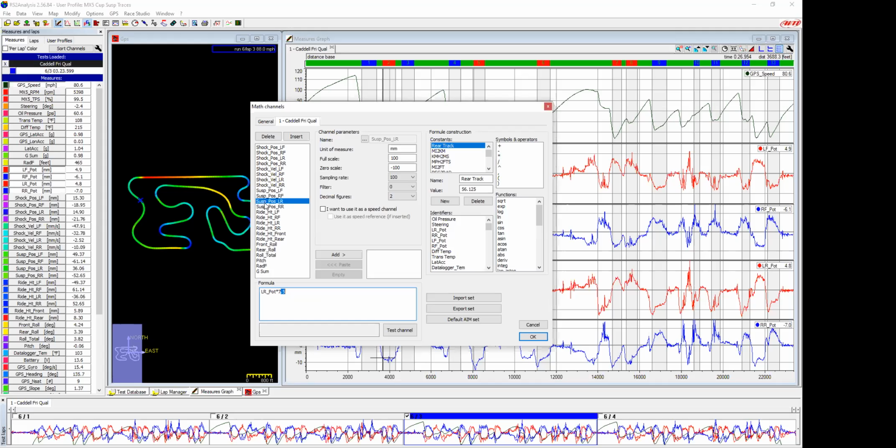Okay, so now I've got a suspension position out there at the outer edge, right? And now I can look at the track widths and the wheelbases, and I can actually see what the suspension is doing based on this math. Okay, and a few more things, and here's the front roll, and I can do the math and end up with, by plugging in the track width across the front, the 57.2958. I remember many webinars ago that somebody asked what that was, and I blanked on it, but that is converting radians to degrees. In our math, we like to use radians, and then at the end you and I understand that this is 20 degrees or 10 degrees. So that's what's converting there.